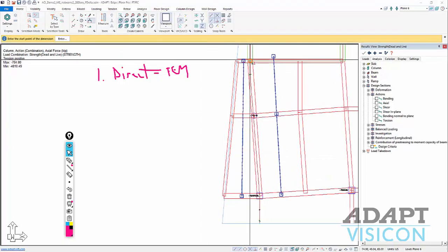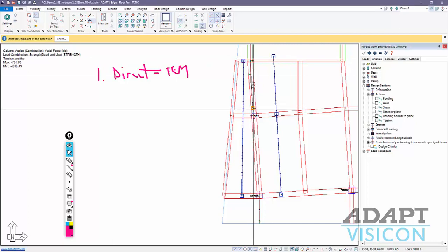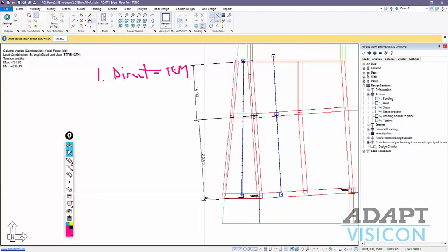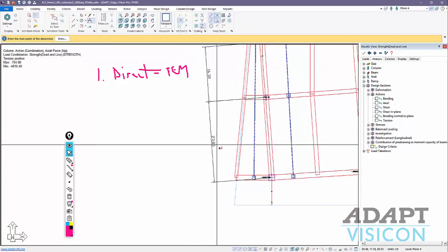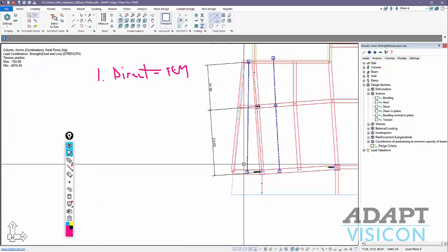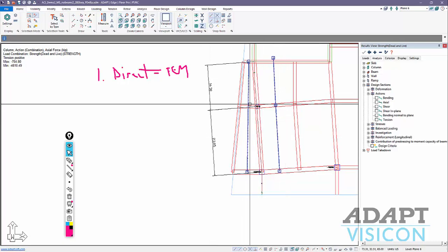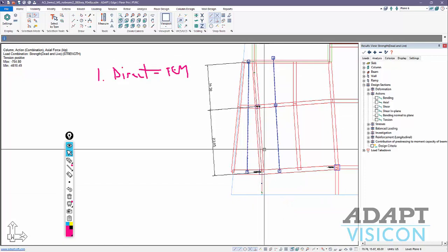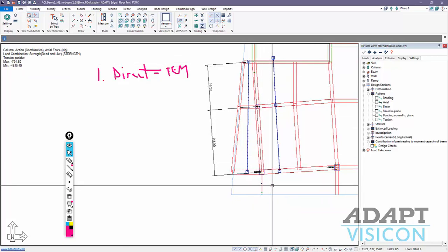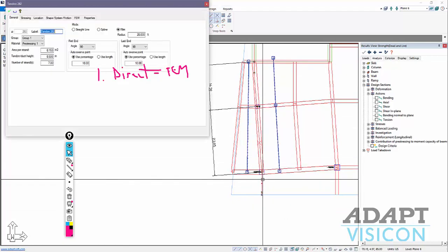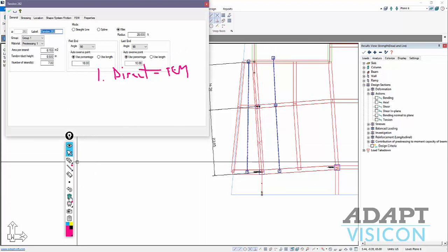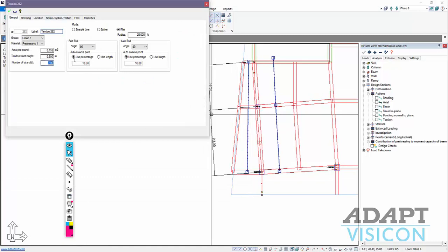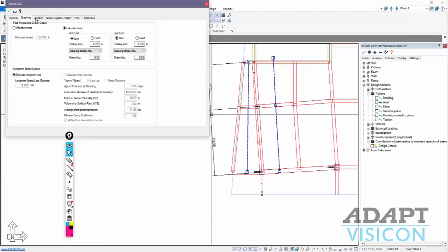this, the tendon starts here at the top end, so I'm going to dimension from there to the point of the concentrated load, and also over to here. And if we take that ratio, this point load happens around 0.4 times the length of the tendon, or the length of the span. So for this tendon, we're going to go into that tendon. Let me go ahead and delete that markup. We'll go into the tendon and enter the properties of the post-tensioning.